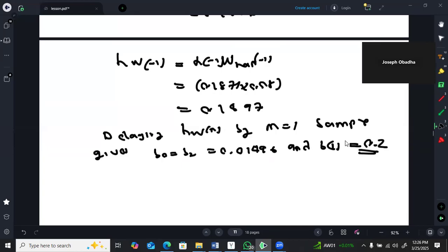So you have seen that the moment we have obtained our filter coefficients using the Fourier transform method, then to get the corresponding coefficients using the window function, we multiply the corresponding values.